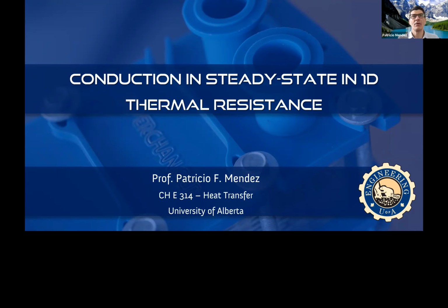There is a case of lumped capacitance. And in that case, our energy rate balance ended up becoming a first order differential equation that for the case of convection was a linear first order differential equation, which we solved and was very insightful. We could account for the time things take to cool down or the time things take to heat up. We could account for the issues of phase changes, like in the case of making snow.